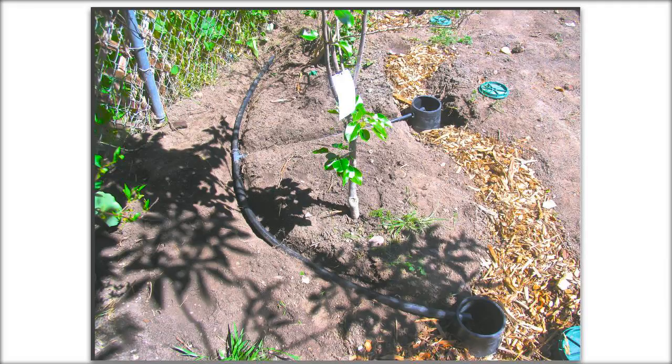Here's a construction picture of the irrigation part. You can see that it looks kind of like a drip irrigation system, except all of the materials are bigger to prevent clogging and to prevent back pressure on your machine. So that main line is a 1-inch line, and the line going off of it is a 1/2-inch line. So we're not restricting the flow in the main line, and we have 1/2-inch lines that are large enough to let the lint and any dirt and debris in the water come out. That's landing in the mulch basin, which is near a plant, and so it's all going to soak into the soil through the mulch, which filters the water and then irrigates the plant.